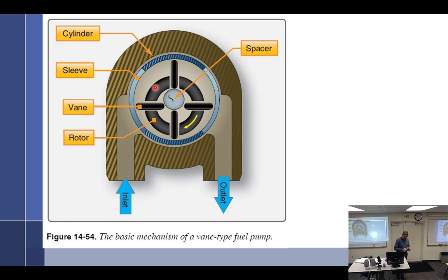This one's seized up. It's all rusty and seized. All right, so it moves around. So fuel gets in this little cavity, right there, comes up in here, gets that little cavity. And then as this goes around, it's going to lock off and not let any more fluid come in right about there. Whatever's in this chamber gets pushed around and out that way. And then there's really not much right here, because it kind of closes off. So there you go. It's going to pump that space times 4 every revolution. Spin it faster, you're going to get more fluid out.